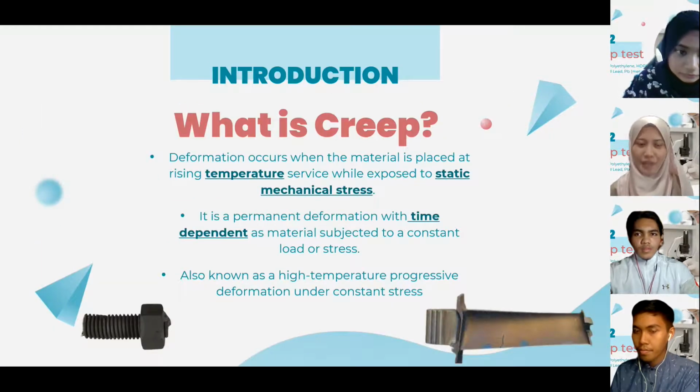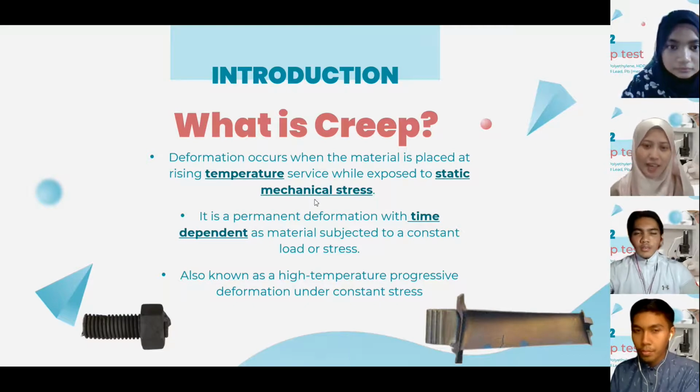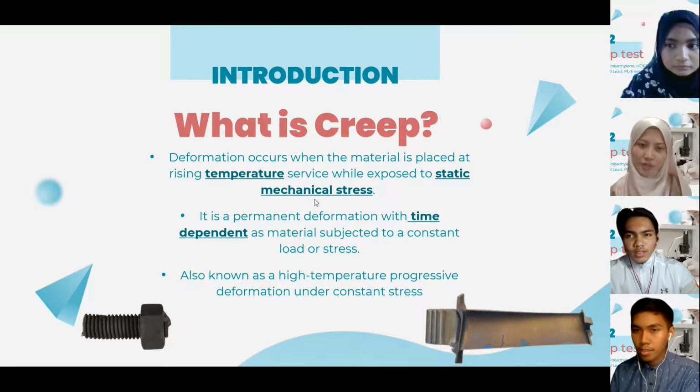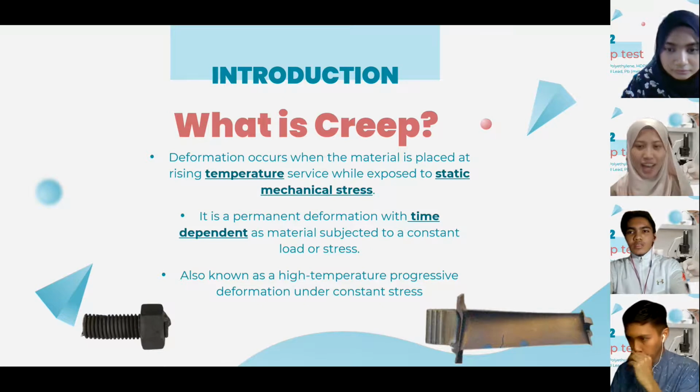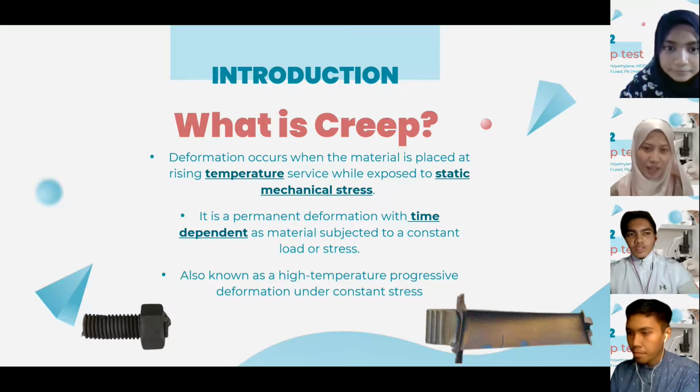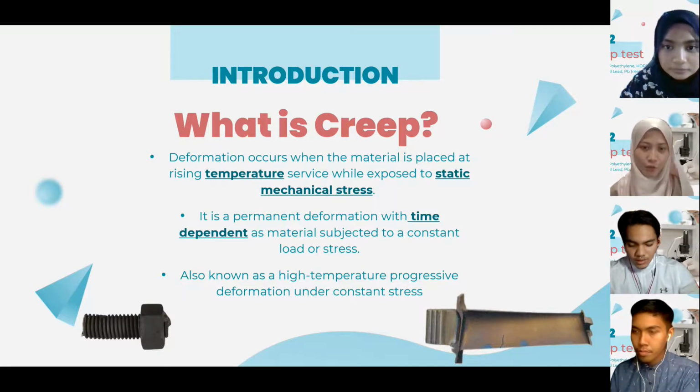So what is creep? By definition, creep is an undesirable deformation that occurs when the material is placed at a rising temperature while being exposed to static mechanical stresses. Therefore, as highlighted in the slide shown, temperature and static mechanical stress or load are the important parameters that can contribute to creep and accelerate or decelerate the process.